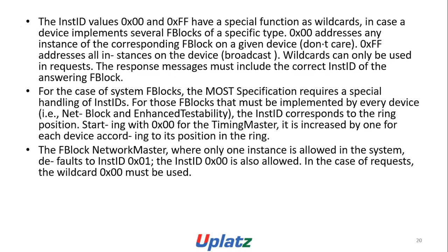The instance ID values 0x00 and 0xFF have a special function as wildcards. In case a device implements several FBlocks of a specific type, 0x00 addresses any instance of the corresponding FBlock on a given device, don't care. 0xFF addresses all instances of the device, broadcast. Wildcards can only be used in requests. The response messages must include the correct instance ID of the answering FBlock.